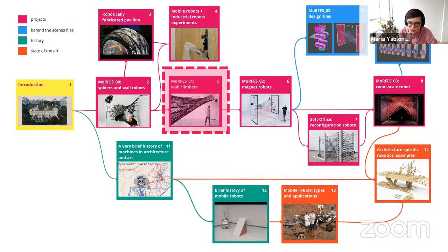In the last project, I had a separate tensioning system that was actually controlling the filament tension. But tension control is a super hard problem to solve, and not as straightforward as one might think. So for this particular project, I had a little subroutine for the wall climber. Whenever it would do the anchoring, it would then drive straight down first. And that helped to pull the filament a little bit around the anchor. But generally, we've done a lot of post-tensioning manually.